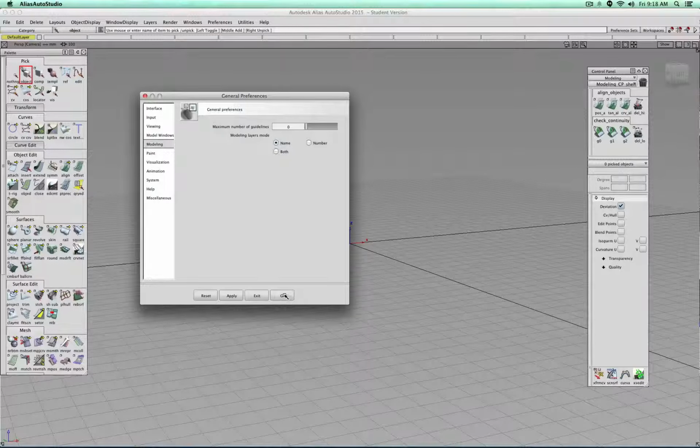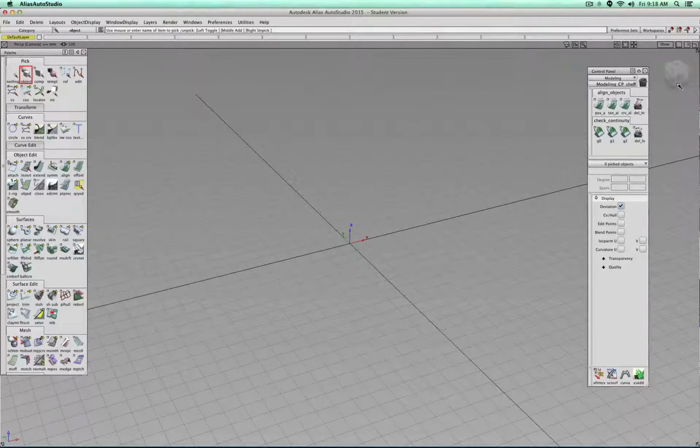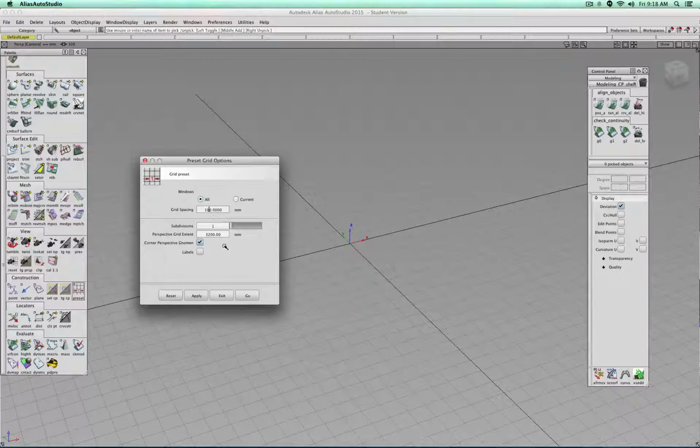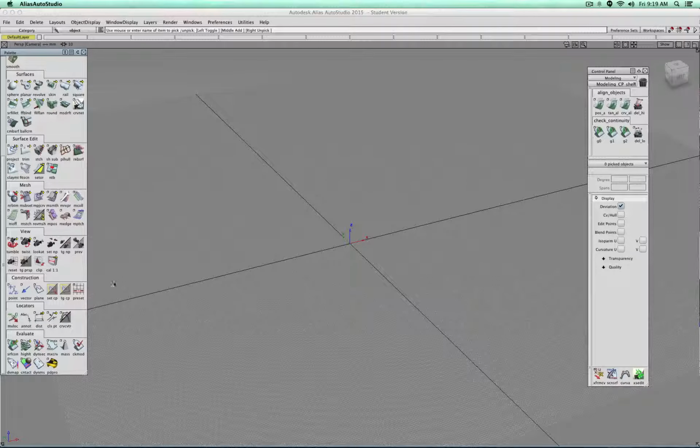Okay. Good. So our blade is roughly 62 millimeters wide. That means our grid spacing is not really suitable. Currently, one cube is representing 10 centimeters. It should be 1 centimeter. So we set this to 10. And instead of just seeing the centimeter, I also would like to see the millimeters, so I subdivide that centimeter into its lower units. Let's take a look.